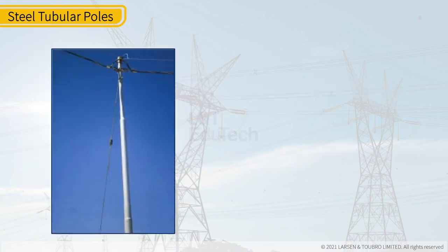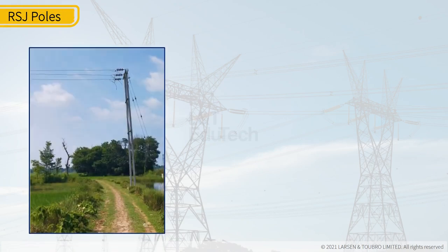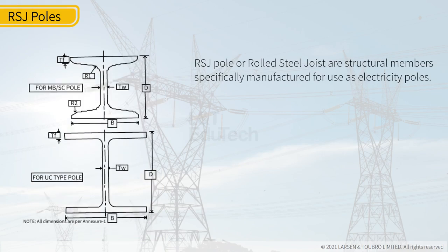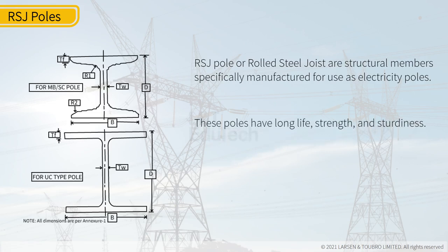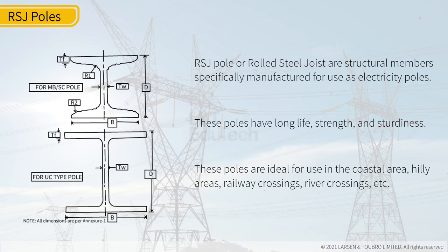Tubular poles are either of swaged section, built-up sections, or stripped single unit type joint-less one casting. These are normally used in hilly areas. RSJ pole or rolled steel joist are structural members specifically manufactured for use as electricity poles. These poles have long life, strength and sturdiness. These poles are ideal for use in the coastal area, hilly areas, railway crossings, river crossings, etc.